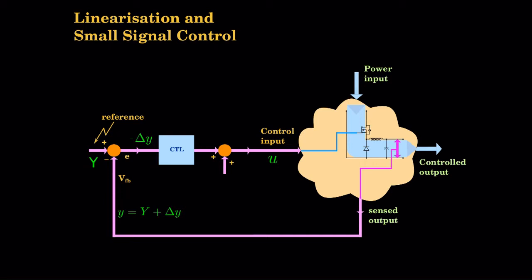So, the moment you use dynamical systems which are not linear and where you want to operate it within a very specific region, induction motor and things like that, you need to put the feed forward term, otherwise it will not be fast, and also the stress and the strain on the controller is very large, and to design for that is difficult, and it will suffer from the dynamics, it will suffer from speed, and therefore. Okay.